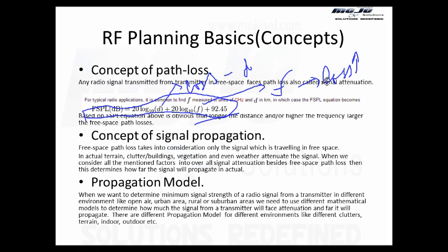So we don't have a line of sight, so the signal doesn't reach us as free space path loss. If we are standing in front, the signal reaches us as a reflection, as a diffraction, as a shadowing. So before the signal reaches our cell phone from the transmitter, it goes through different phenomena. What signal strength we will receive is very difficult to predict, and that's why these planning tools are so popular, like ATOLL or Asset.